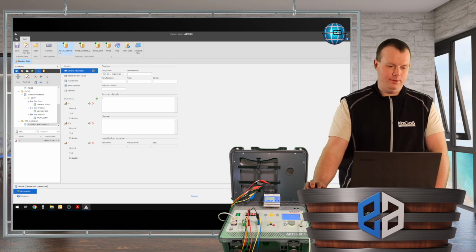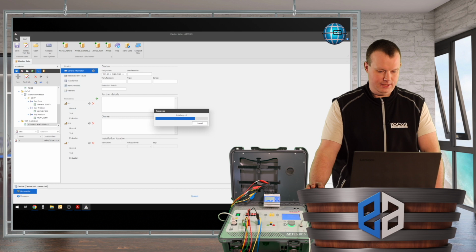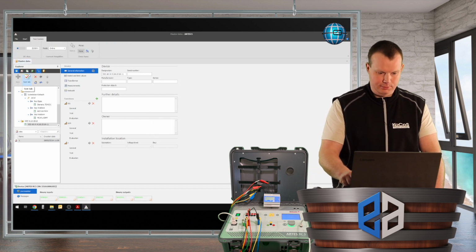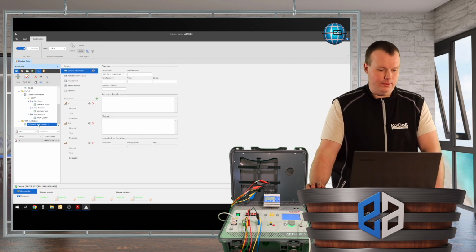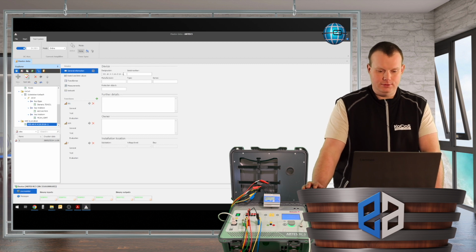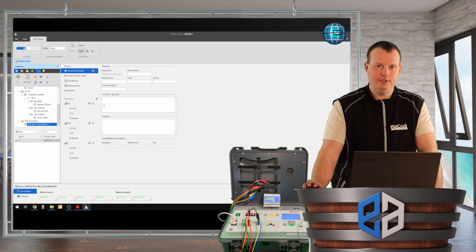For the first step, we connect our ARTES RT3 and we start the auxiliary voltage for the relay so that it is working. Now, while the relay is booting, we will check the preparation for a corresponding relay. I already created the relay and I inserted the corresponding functions for frequency and voltage protection.